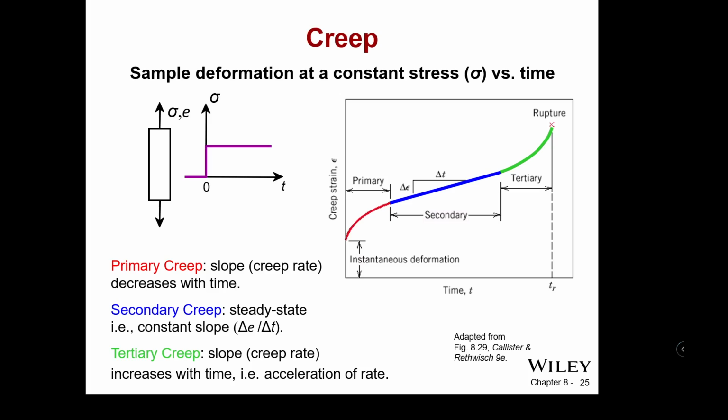But as you continue to apply that load, you're going to have the material slowly begin to creep until you start to reach this tertiary phase. You have an acceleration, and then ultimately what would be the rupture, where all of a sudden a tube wall collapses because of the stress at an angle or whatever is happening there. All of a sudden that collapses, and then the whole board collapses because you get an acceleration of this rupture. So that's exactly what creep does.